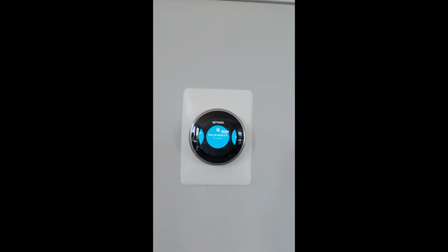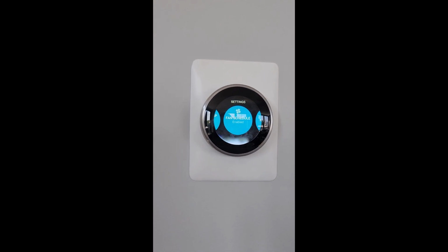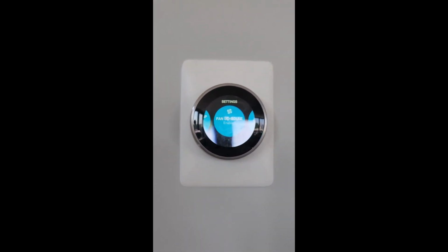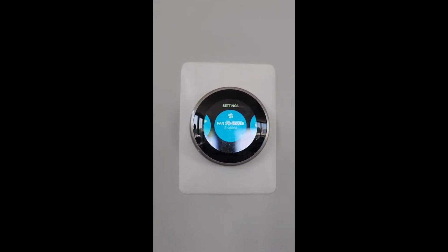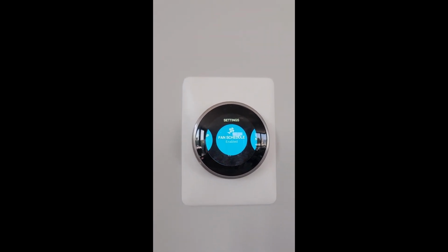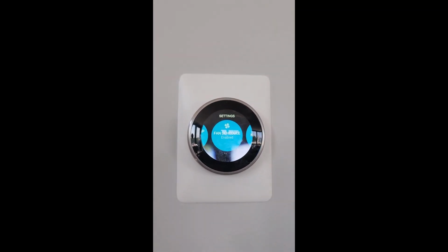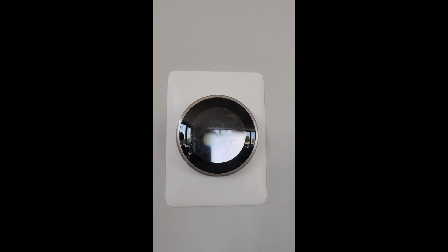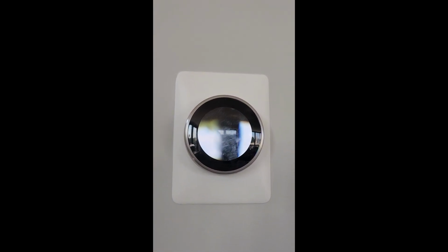So once again, we have a really solid jumping off point. There is a chance it is the thermostat, but I would say there's a pretty small chance of that only because the thermostat is signaling the compressor, but not the fan. There's also a chance that it is the board, where the controller of the HVAC unit itself is not signaling the fan, or possibly the relay is not clicking because it has gone bad. And of course, there is a great possibility that it is the fan itself.